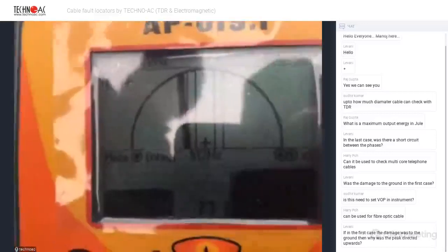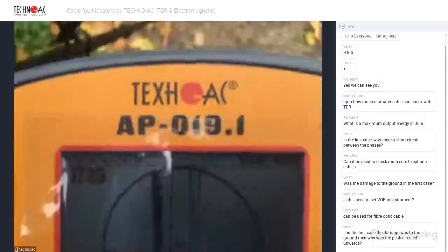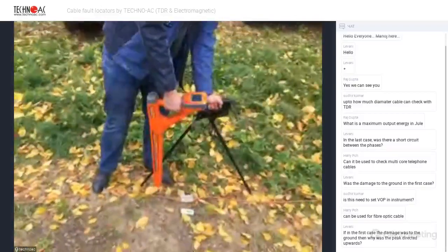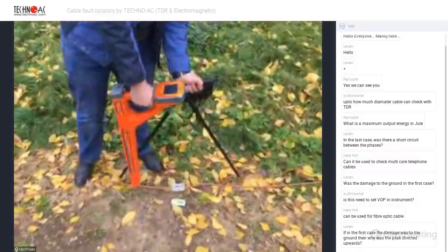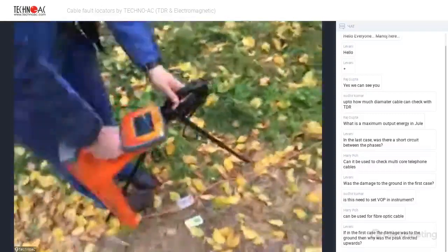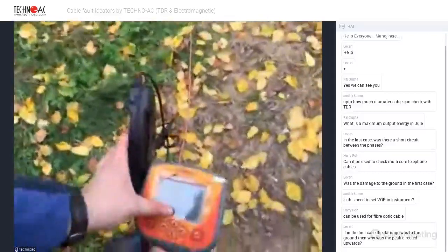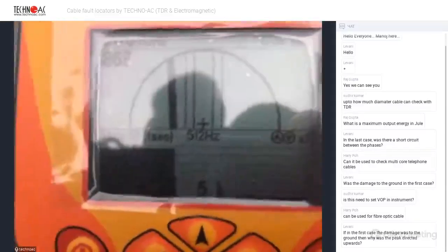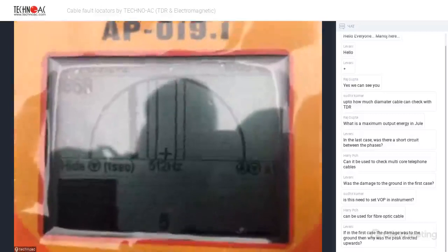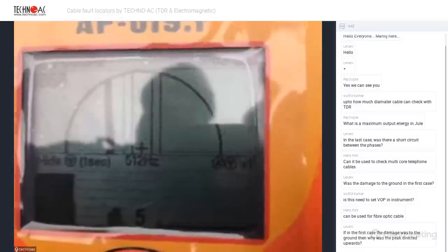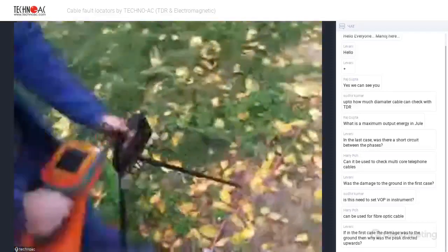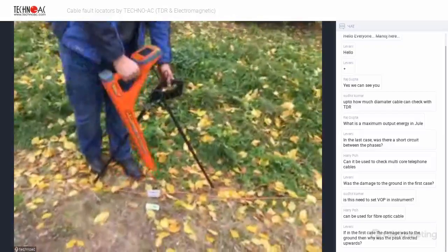You see? So this is how we can tell that possibly we have located our damage. But when we put the damage right between the probes of our sensor, we will be having the lowest possible signal, 4. So when we directly put the probe in the spot of damage, we had 60 something, and now we're having 5, only 5. And the sensor is positioned right above the damage, you see.